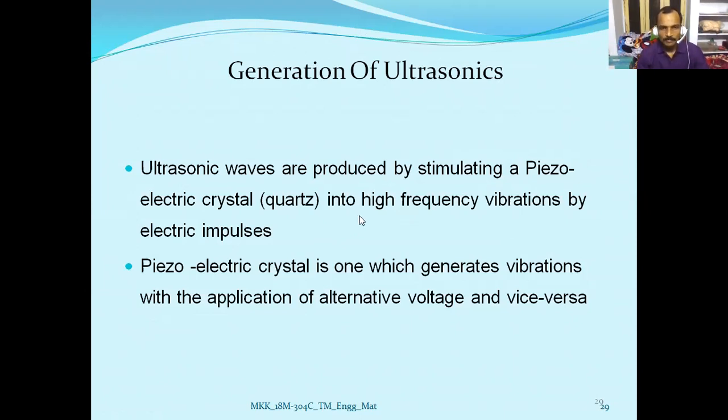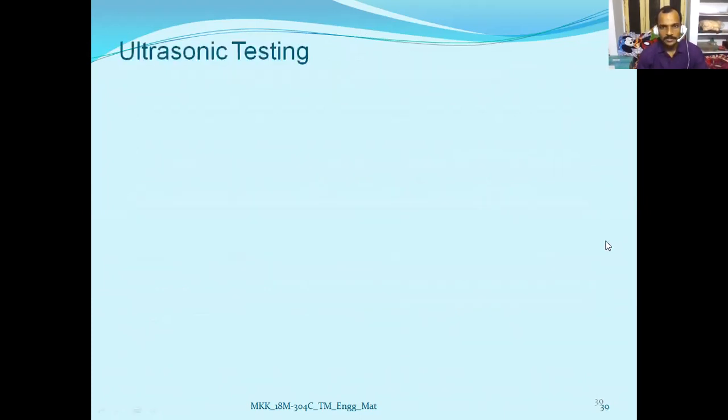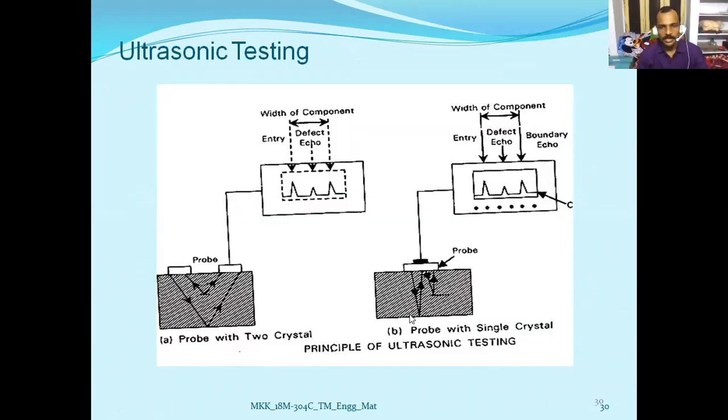So a piezoelectric crystal is one which generates vibrations with the application of alternating voltage and vice versa. Let us have a look at this particular diagram. Here let us see the ultrasonic testing. This is the specimen in the first case.